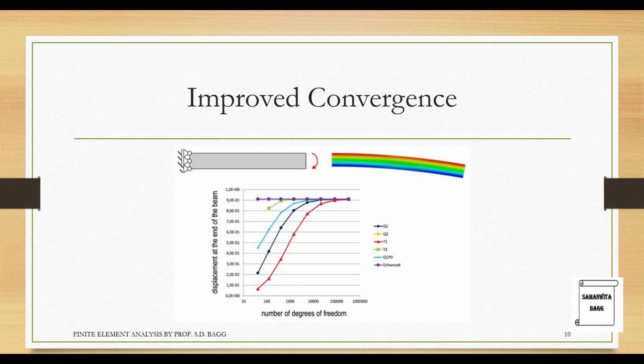Let's talk about this convergence. We have discussed convergence of CFD element, or you can talk about convergence even of the stresses which are occurring on a beam, or the deflection at the end of the beam, or the number of degrees of freedom, as you can see here.